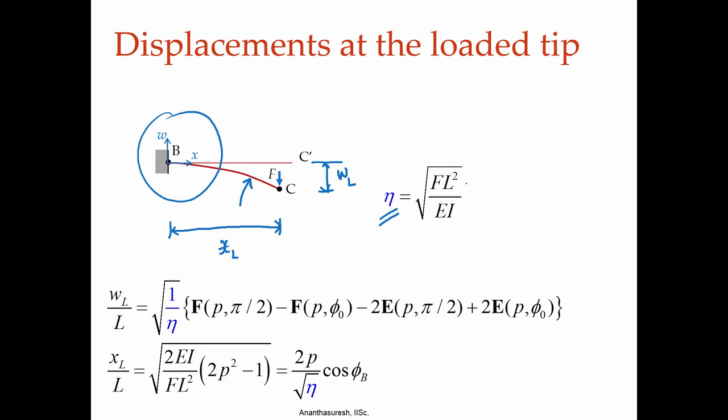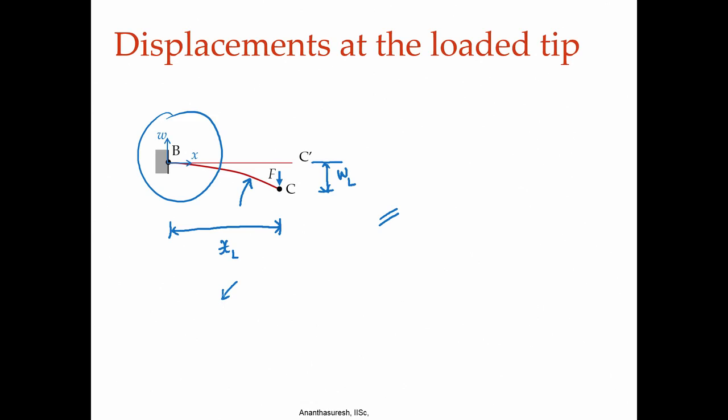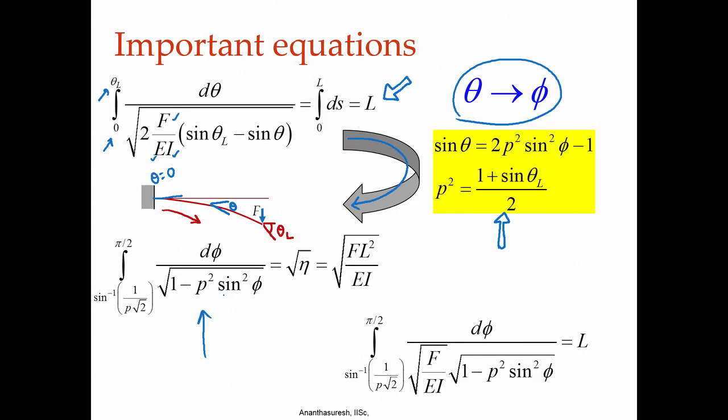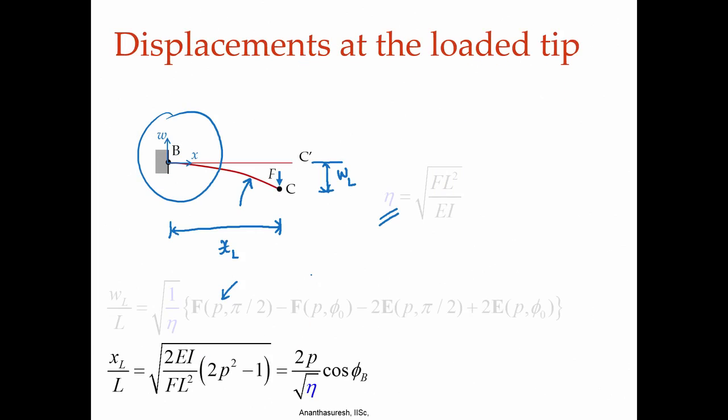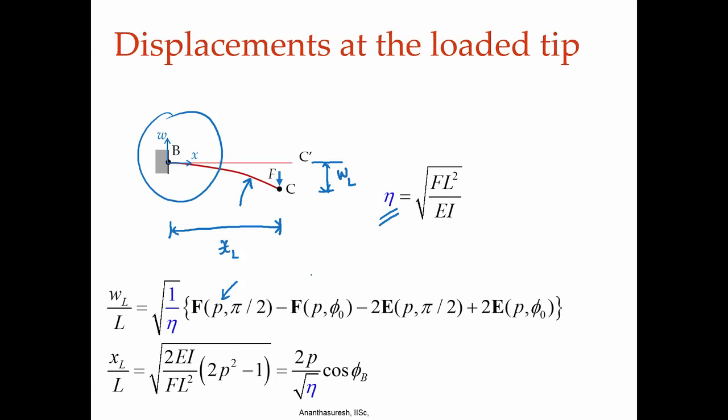Before and after we assume that the length is the same, Young's modulus E, second moment of area I, and then there is this P that needs to be solved. If we go back to the previous slide, that P depends on this value eta. So, if I know eta, I can calculate P and vice versa. So, we have that P depends on eta.